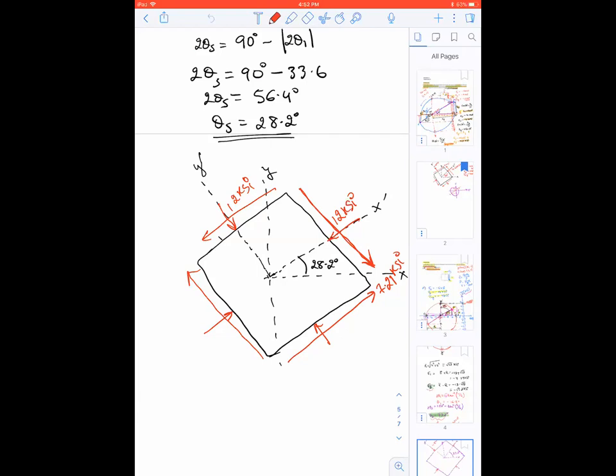Or for the stress transformation equation, I'll say use the stress transformation equation to calculate the principal stresses and their direction, things like that. A lot of the time I ask students to recognize the X and Y faces and then X prime, Y prime faces and read them from the Mohr's circle. Maybe I'll give you the Mohr's circle and ask you to read from there. So it is important that you practice, okay?